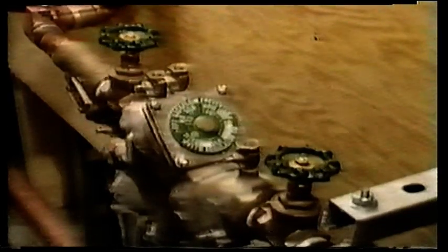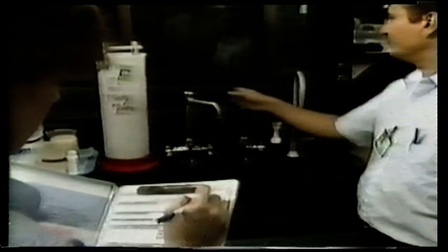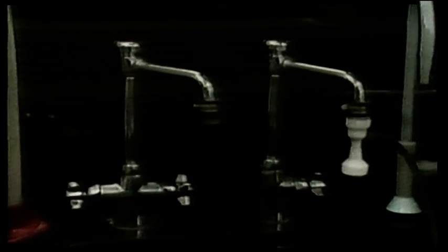The entire laboratory area is contained through internal protection with separate reduced pressure principle backflow prevention assemblies on the cold and hot water supplies. Since laboratory gooseneck faucets are a hazard, this protection is augmented by atmospheric vacuum breakers at each outlet. Each facility has different specific hazards.